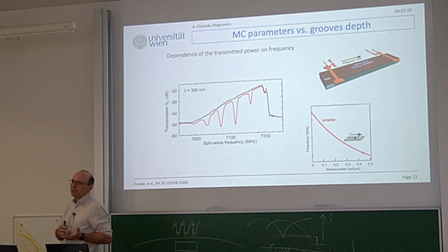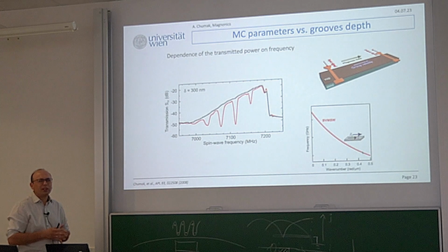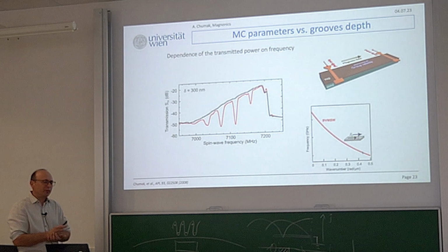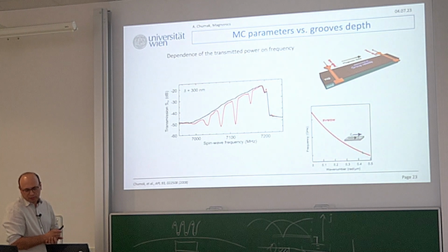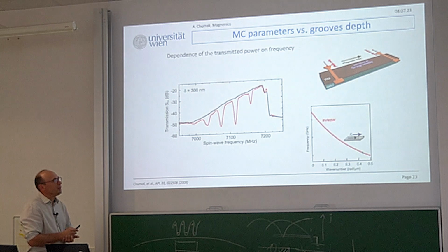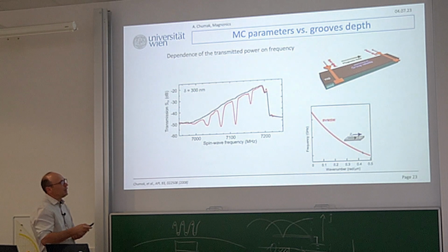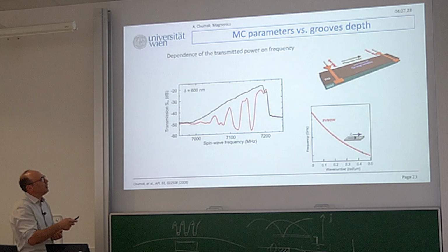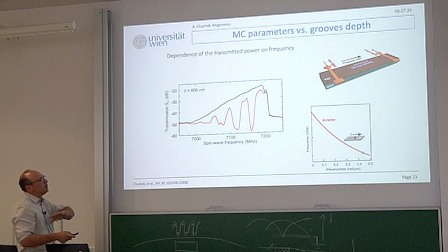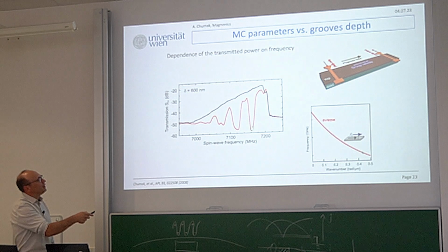Therefore, what was done: we had this structure and placed a mask. We can use silicon oxide, but then it doesn't work well. So we developed another technology in Kaiserslautern, simply an organic photoresist, which was baked properly so that it becomes stable against the acid. We etched 300 nanometers and measured transmission, and we see band gaps. Then we etched with a step of 100 nanometers and measured again. So I was running between the clean room and the lab. But for 600 nanometers, you see that it's getting much deeper.